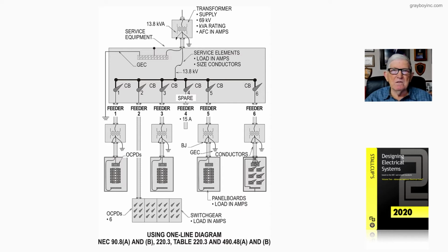And it's based upon the type of loads that you're calculating that are over 1,000 volts. And then the terminal ratings for systems over 1,000 volts, 110.40. The terminal ratings now for 1,000 volts or less, 110.14, C1, little a or b, depending upon the voltage.